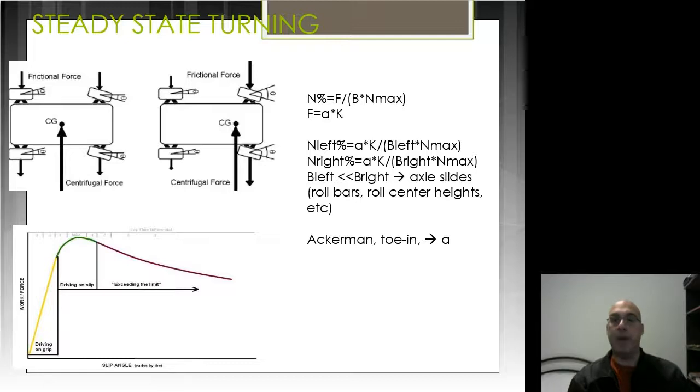So it's the same principle, but I achieved it with dampers, which means that you had that oversteer going into the corner when you applied the cornering force, and it made the front end ripple a little more going into the corner. There's a whole bunch of other ways to do it, stiffer springs.